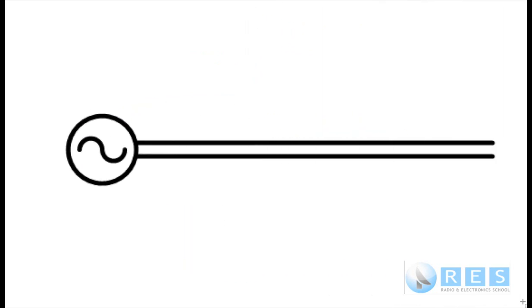Let's talk a little more about this thing called characteristic impedance. The symbol for impedance is Z, and Z0 is the symbol for characteristic impedance. I've got a transmitter, I've shown it as an oscillator. That's a radio frequency transmitter, and I've got a transmission line. Let's imagine that this transmission line is of infinite length. Goes on forever. We couldn't build such a line, but we can build it in our heads.